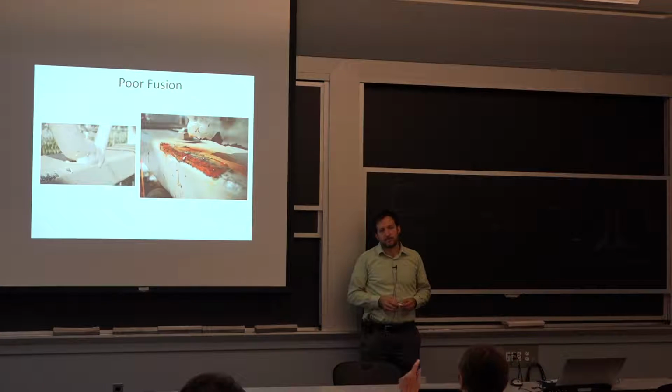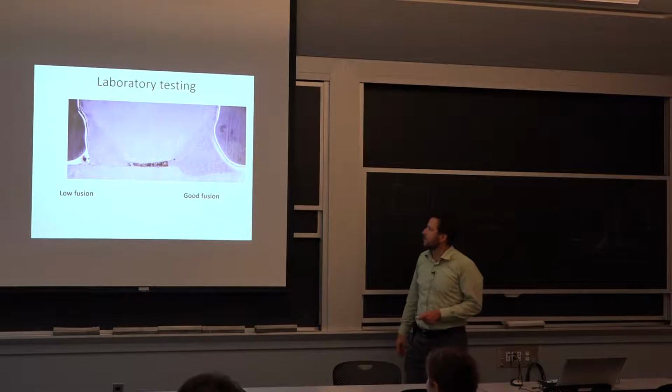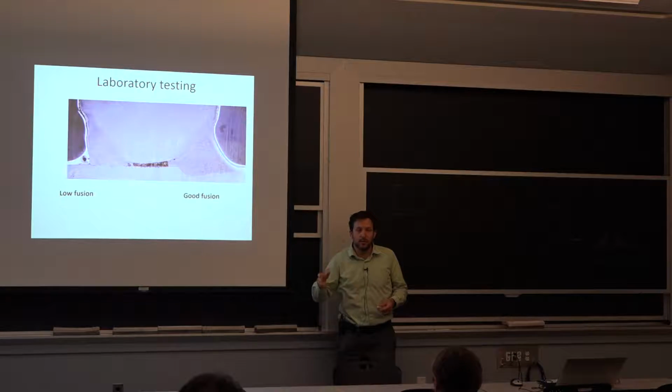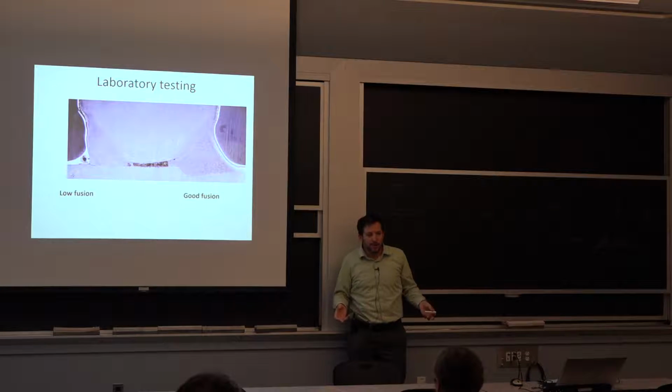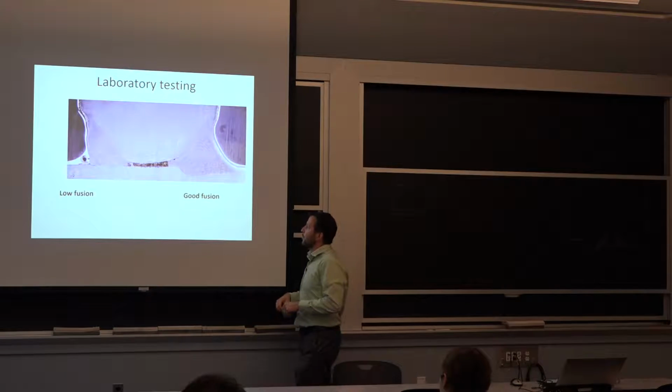Are you concerned with burn through the hollow part? Yes. And you will see that in that section. That's a very good question. So one reason, and this is on the repair. So this whole process is, they had a little bit of an overload, not a big overload. Then they called on inspectors to look at the weld, and every inspector said these welds are not good. You shouldn't be using them because they won't behave in a ductile way. You never know when they're going to snap, and therefore they're not reliable.